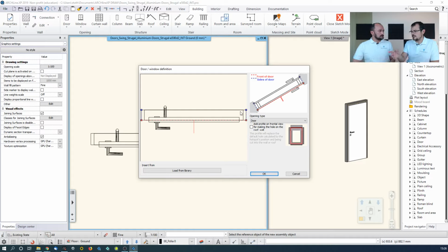Why do you have to do this? Why don't you just slap this object onto the wall? Because this way I tell the software which side is the left and which is the right side. As you can see, there's this little tiny symbol telling you what to do, and there's this little sticky part which is the front of the door. This is an arrow pointing to the direction where the front of the door is.